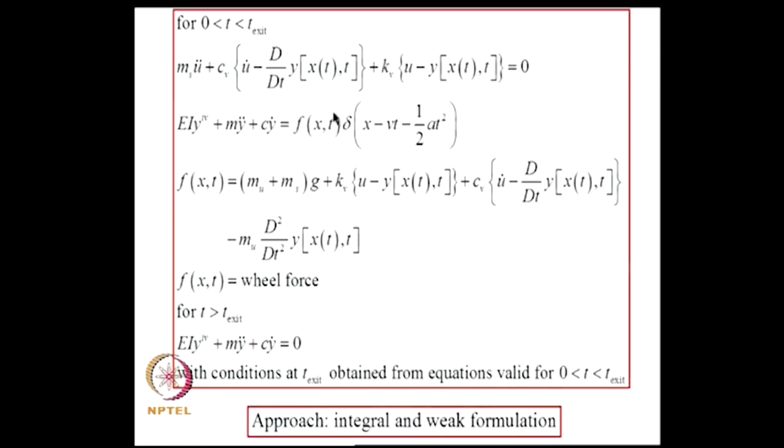So, what we will do is we will try to develop a finite element model for this pair of equations, an ordinary differential equation and a partial differential equation, by using what is known as an integral and weak formulation. In the development of the finite element method so far in the course, we have started with the variational principle. We did not start from the governing differential equation. When we started discussing approximate methods, we saw that the way we apply the Rayleigh-Ritz and Galerkin methods were somewhat different.